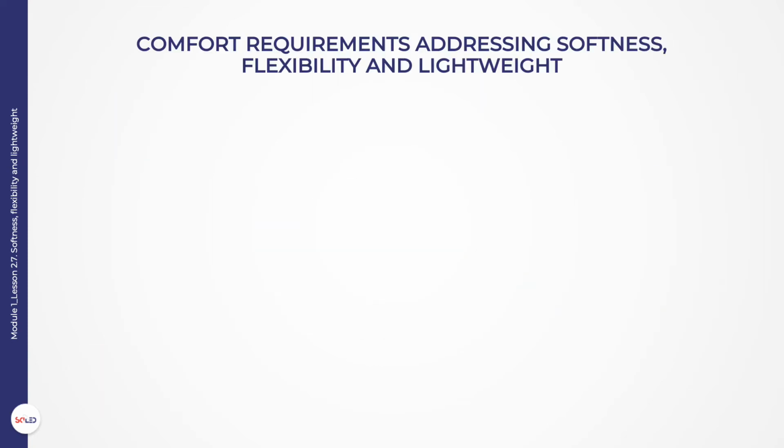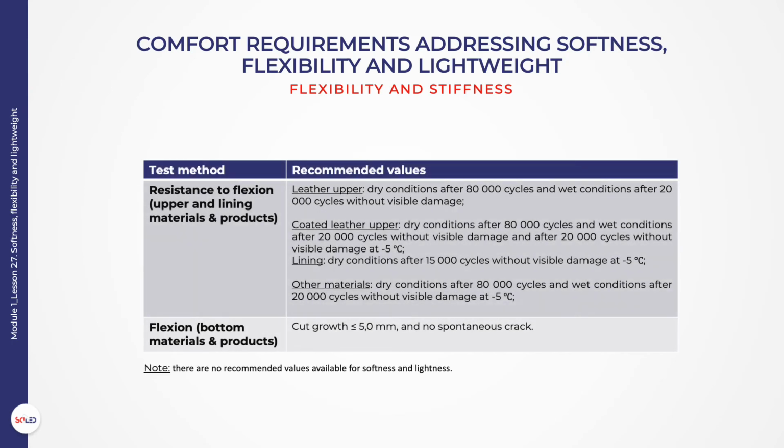Comfort requirements addressing softness, flexibility and lightweight. Previously it was referred that flexion resistance is the number of flexes that the footwear is subjected to until there is a cut growth and/or initiation of cracks or otherwise fail as flex increases. The use of non-flexible materials requires a design in such a way that does not compromise the comfort of the footwear.